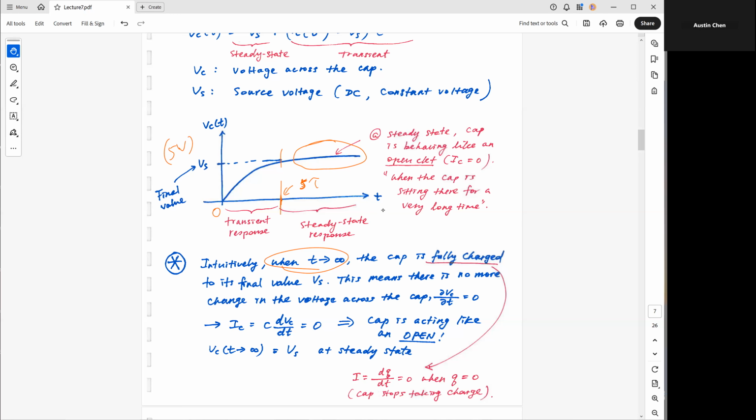It has to be, because it has been sitting there forever. I use 5 volts over here. If it's already charged all the way to 5 volts, there is no more room for this voltage to change. It's saturated; you cannot go up nor down anymore. It has been fully charged already.